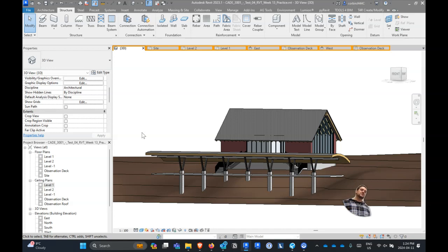Yeah, and even to build that from a real world perspective, we've actually looked at doing curved timbers in a few projects, and it's possible. But one thing they often do is instead of curving a timber, they'll take a 24-inch timber and cut the curve out of that timber. So they're not actually curving the beam, they're just making it curved by cutting it. When you use glulams, like the new Limberlost building that we will be moving into, hopefully before you guys graduate, in January,